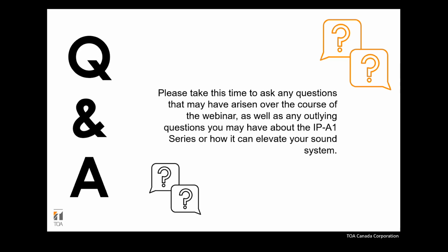So we actually got one in chat just a moment ago that we can touch on first. The question is that we have 4 amplifiers, but 2 power supplies. Please explain how that provides independent power to each amp. Yes. So the 2 power supplies are fed into the VX2000DS. The VX2000DS outputs and distributes up to 6 output power channels, each capable of feeding up to, I believe, 600 watts per channel. And from the VX2000DS, each module and chassis is fed independently from those 6 outputs.